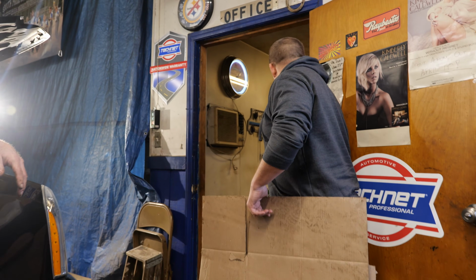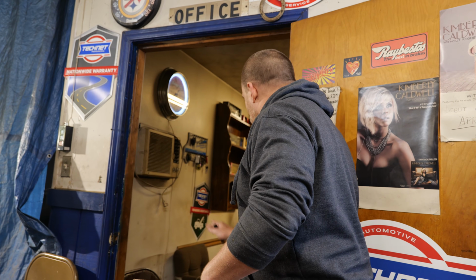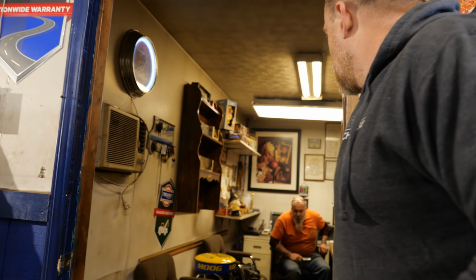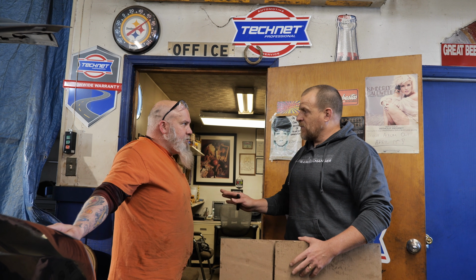This Ford, it runs fine. So give me a history. It died, I guess, and didn't start up. Okay, good. So it happened before, and we put that fuel pump module in there about 5-6 months ago. Then it was good. So the module or the pump itself was replaced? The module that's in the back by the gas, by the spare tire. But the pump was never changed. No, the pump was never changed.